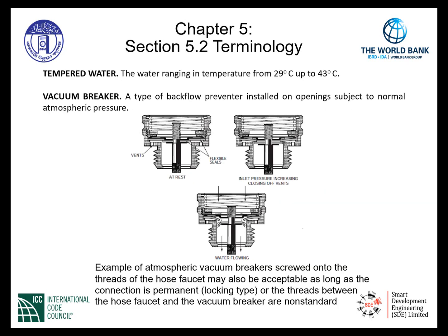Tempered water is water ranging in temperature from 29 degrees Celsius up to 43 degrees Celsius. Tempered water is specified in areas of the code regarding certain fixtures. A vacuum breaker is a type of backflow preventer installed on openings subject to normal atmospheric pressure.